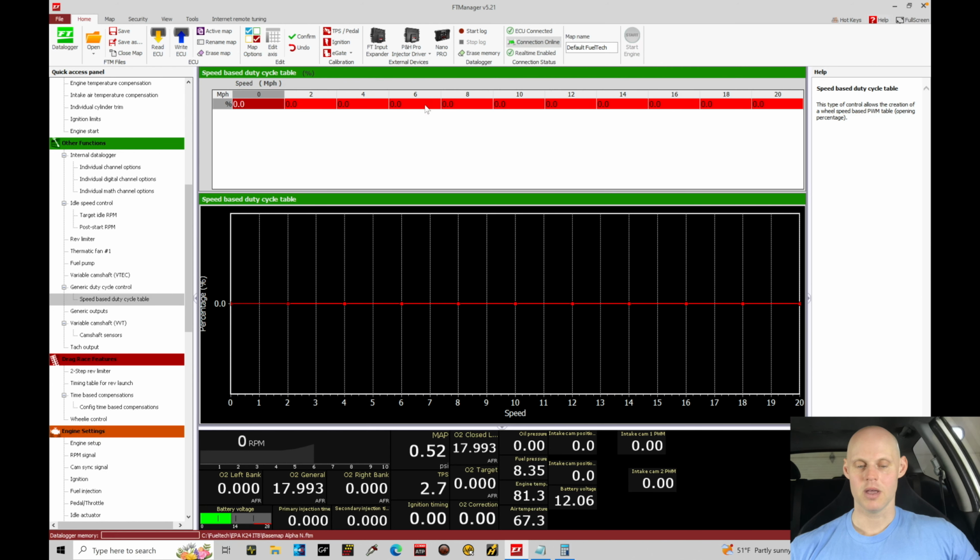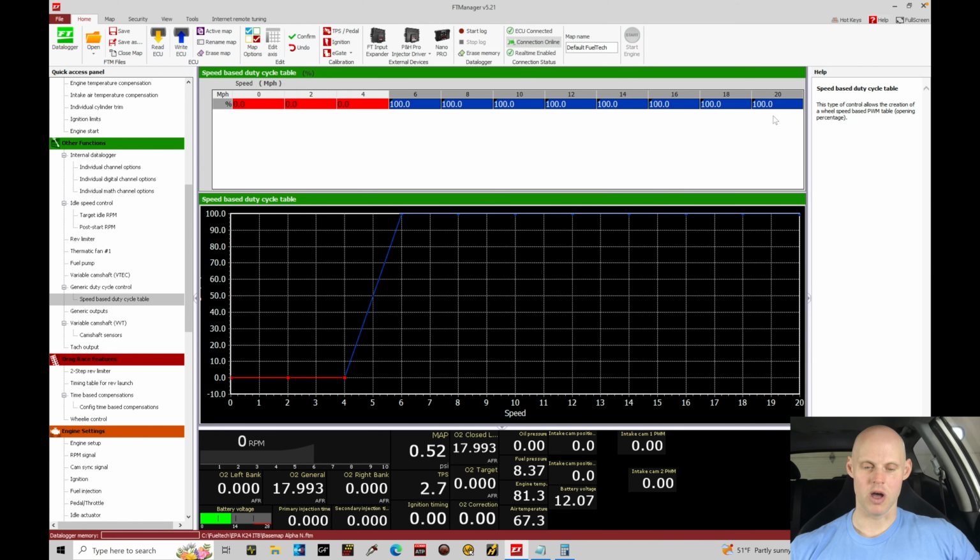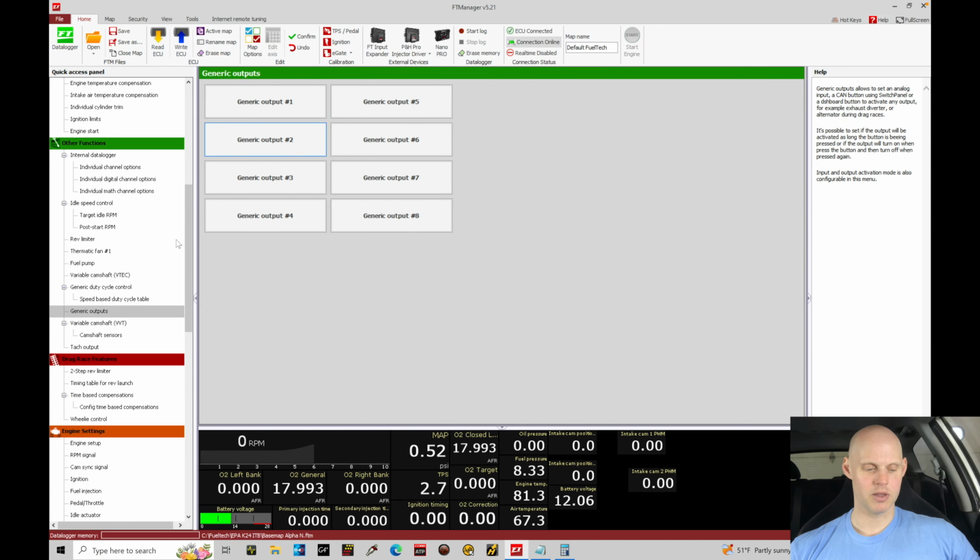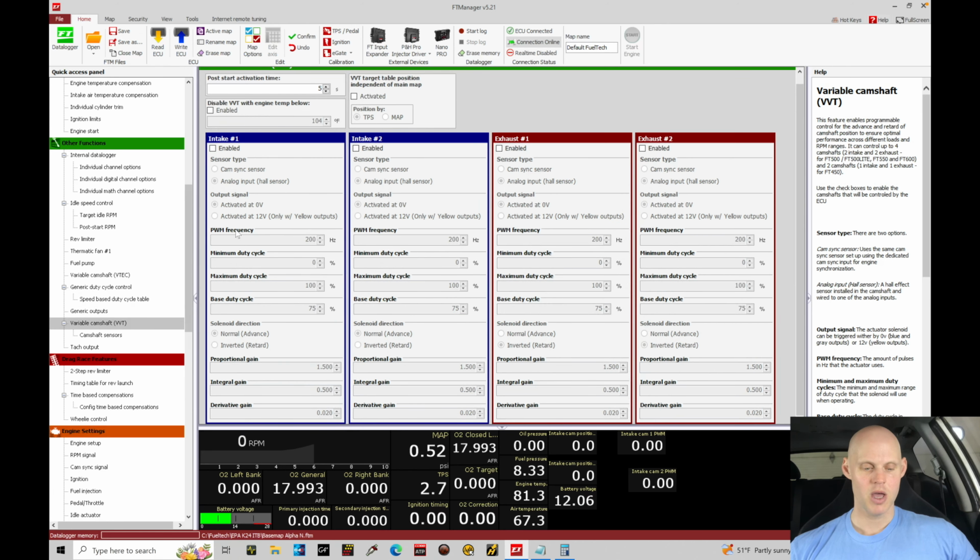And now above 6 miles per hour here, I'll set this to 100, and then I just click save right there, Control S. Below 4 miles per hour, we're going to leave it at 0. So we're allowing it to go into reverse below 4 miles per hour. Above that, we're going to have that reverse lockout solenoid enabled. If we're shifting through the gears, we go into 6th, and we accidentally try to get it into reverse, it'll block you out. So this is for 6-speed only. 5-speed doesn't have this. Kind of some details there. Generic outputs, I'm not doing anything with this. Variable valve timing. We are going to set...